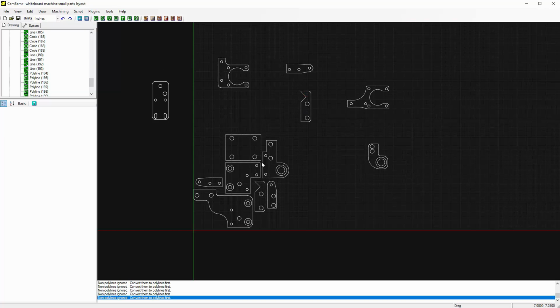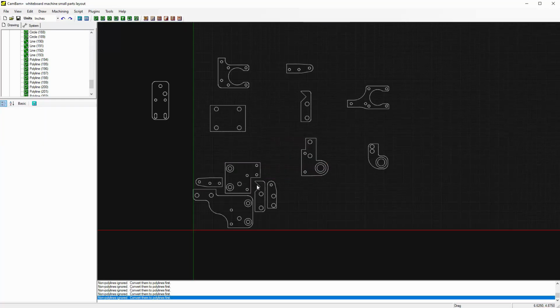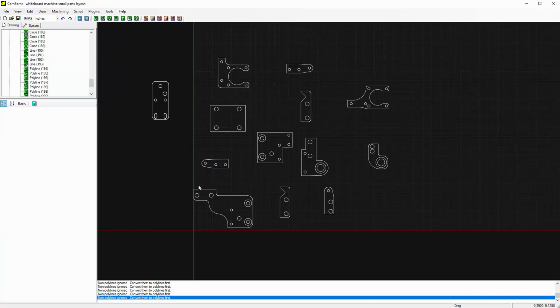here. Before I move the parts to their final locations, I will do all of the machining operations, like drills and profiles. Drills are machining operations that can create holes equal to or larger than the diameter of the end mill. The way a drill operation with a small end mill can make a larger hole is by a spiral movement that removes a large area of material. This will be more evident when the toolpath is generated later.